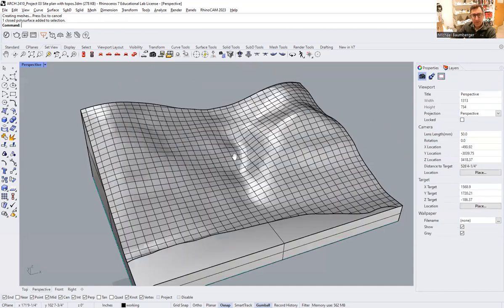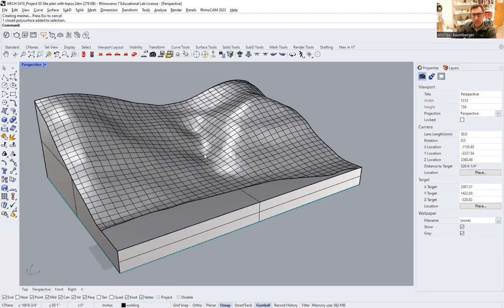Okay, so that's the goal, right? Now we can use all of our Boolean operations on this. It is, I believe, a much more useful model, because you can always explode it to go back to surfaces, right? It's much harder to go from surfaces that have been manipulated to a usable solid model than if you start with a solid model, right?